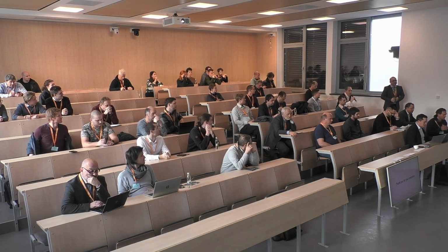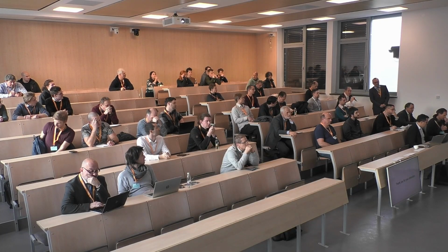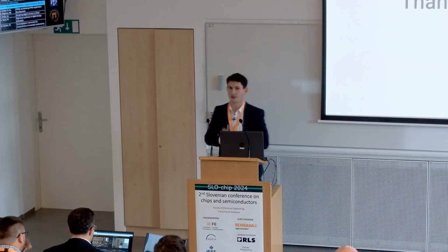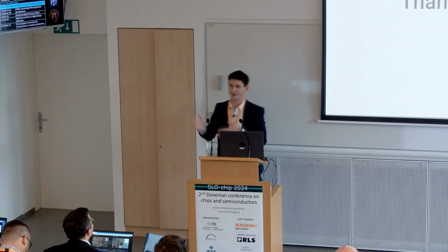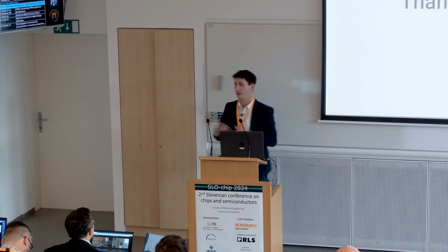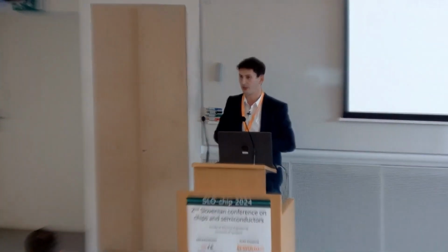Thank you for the presentation. I wonder, is PYNQ tied to a specific device family or board, or can it be exported to others? Concerning PYNQ, it stands for Python Productivity for Zynq devices. So it's primarily targeted at Zynq devices, but it can also target Alveo devices, where the host processor is not the embedded one on the board, but the processor on the node or PC. But still, you cannot use PYNQ with every FPGA device from the Xilinx vendor.